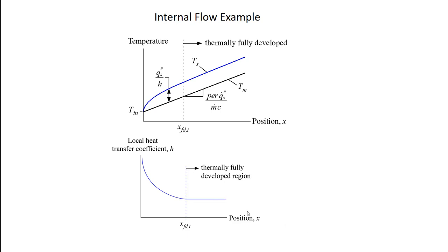So this is the case we talked about the other day where I have a constant heat flux. So if I think about the mean temperature, I go in here at like 77.8, and I just decided that I heated it up to about 200, right? But the surface temperature, which is the conductor temperature, is hotter than this mean temperature. So what I really want to know is how hot does the surface get, right? And that's where I start to think about the heat transfer coefficient.